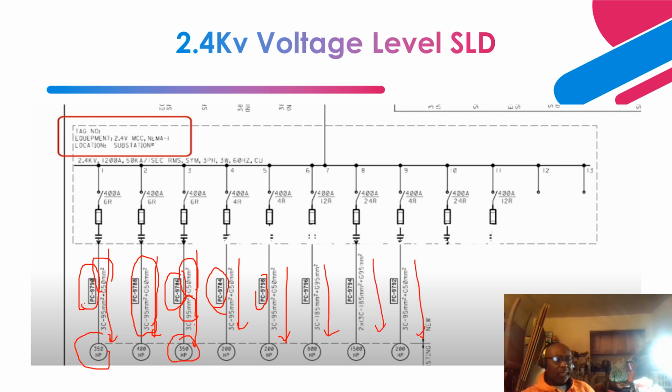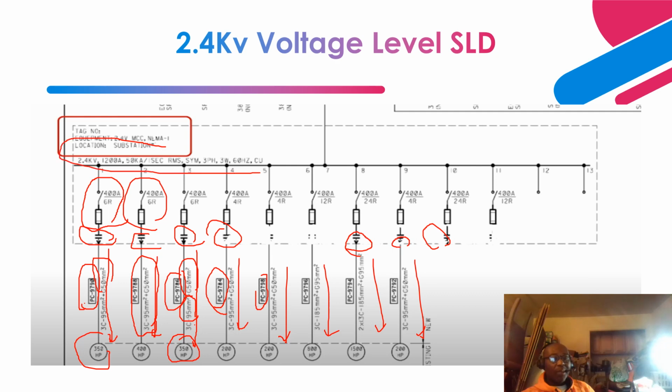Like I indicated, these have contactors instead of breakers, because you can operate contactors tens of thousands of times. A breaker would degrade and cannot withstand that amount of operations. So that is why they utilize contactors instead of breakers, and you have a fused disconnector switch as well. This is the rating of the bus.